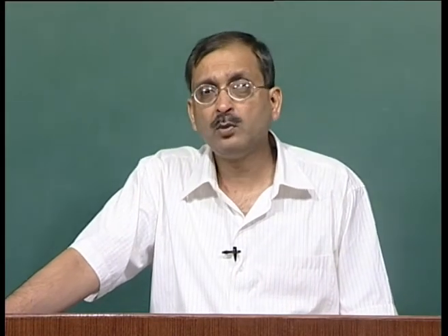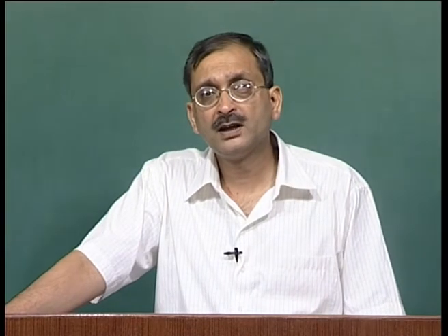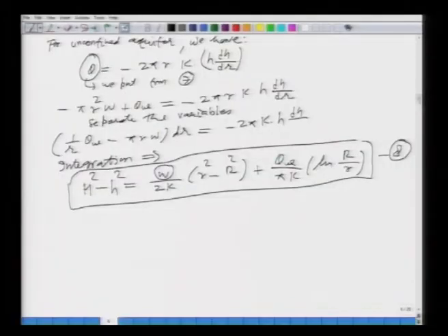So, this is a very important equation which can be used when we have recharge taking place in the unconfined aquifer. If you look at a special case of this, we can determine what the discharge at the well would be. Equation 7 at r is equal to capital R, what is q?